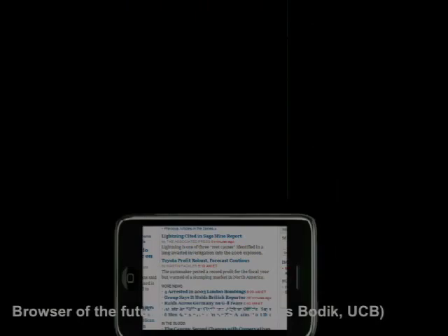Combination of the accelerometer and the camera. That's a pretty good idea. What would happen if you just used the accelerometer by itself without using the camera? Yeah. You have to integrate the accelerometer values, and you probably have such a huge error. Yeah, that's actually a very good point.